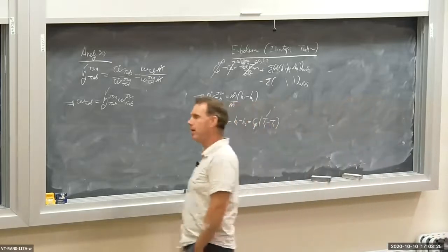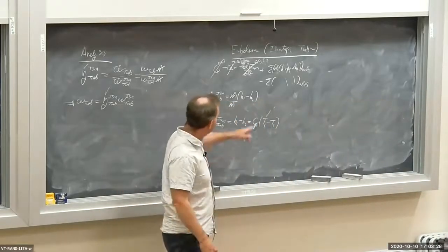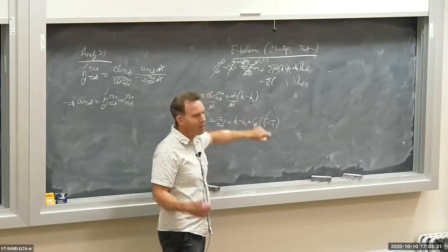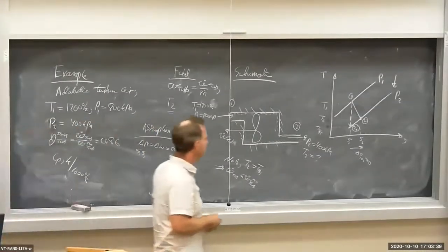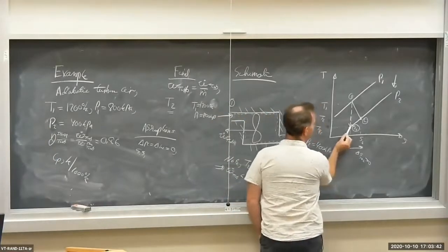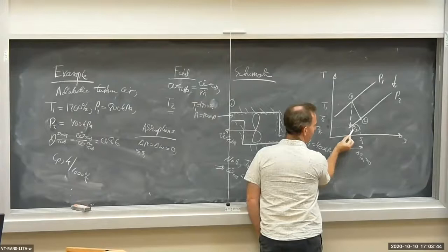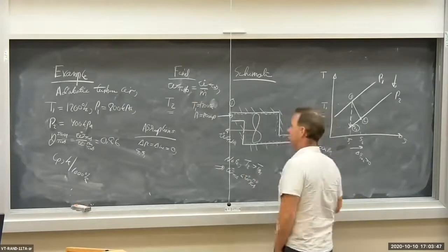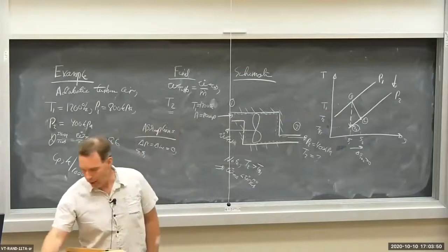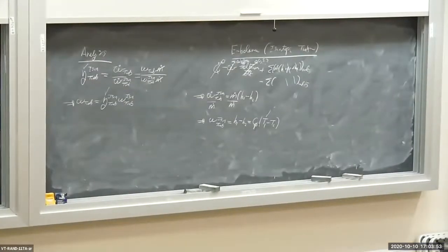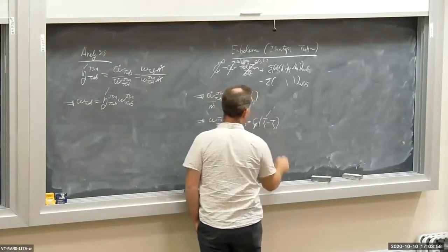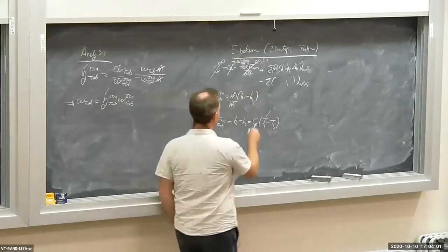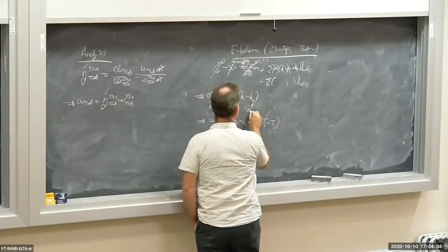By the way, this temperature T2 here and h2, let's go back to our T-s diagram. Is this right? Remember, we're working on the isentropic turbine. State 2 for the isentropic turbine is actually 2s. 2s, that means isentropic. So I am going to put a subscript s on all the 2's here. So put a little s here and put a little s here. Okay? Isentropic.